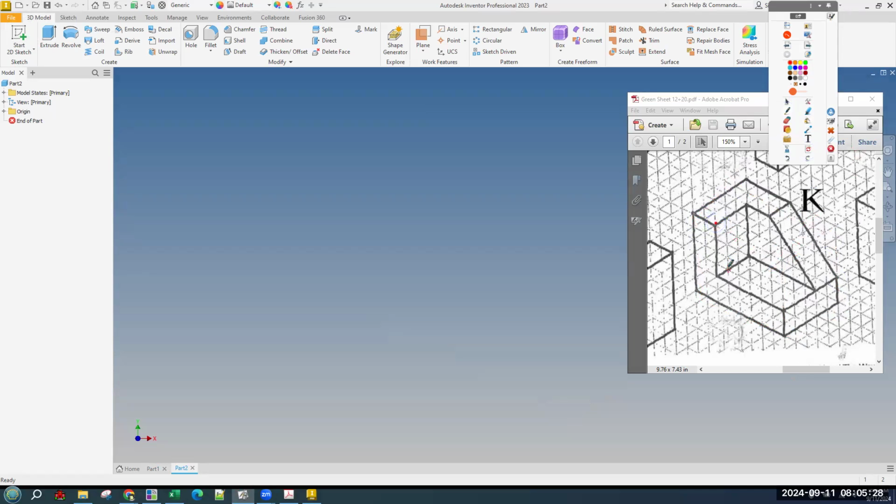One cutaway is going to be sort of this shape, except it has to be on the top. And that rectangle will cut extrude. And then the next one will make this line with what's left over and cut extrude that up.